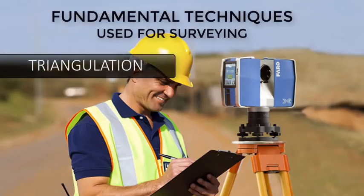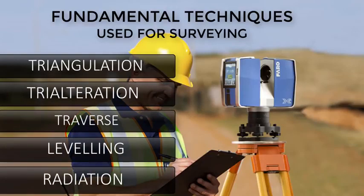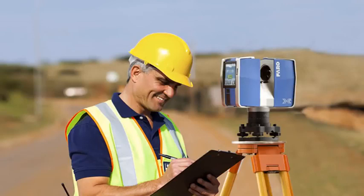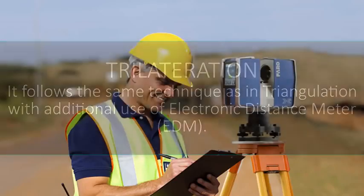Fundamental techniques used for surveying are triangulation, trilateration, traverse, leveling and radiation. Triangulation. In this technique numerous triangles are interconnected and overlap to measure angles from a surveying station. Trilateration. It follows the same technique as in triangulation with additional use of electronic distance meter.